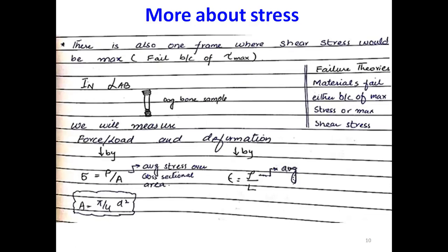Also, when we are rotating the coordinate frame about the point within the material, there would be one particular frame where the shear stress would be maximum, and the normal stresses along the diagonal would be average. We are also interested in finding out the maximum shear stress because, depending on the loading conditions, there are materials or conditions where failure occurs at the planes of maximum shear.